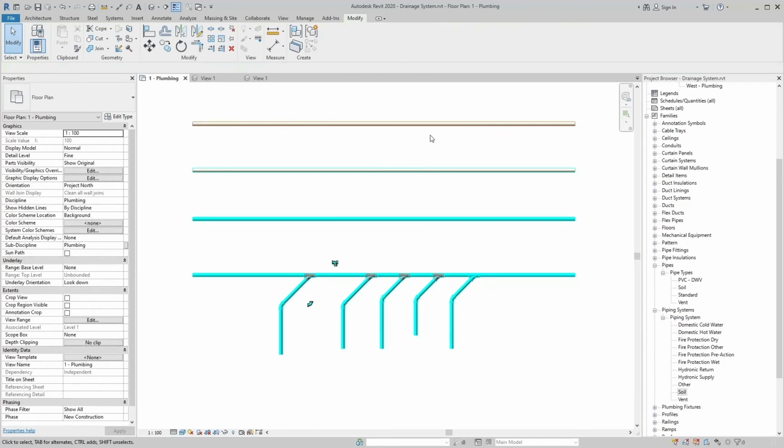Vent pipe is never installed on the bottom, right or left side of a sanitary pipe as waste may block the pipe. Therefore, vent pipe is always installed on the top side of the sanitary pipe.